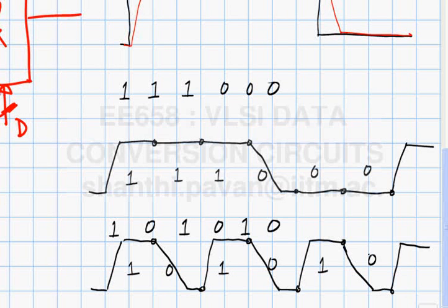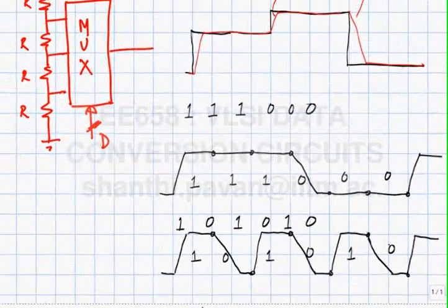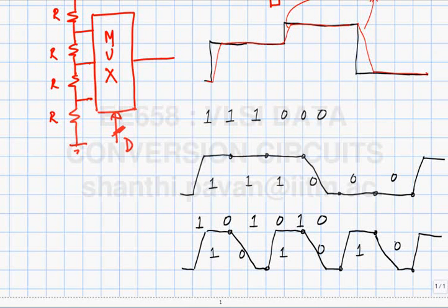So finally you want the DAC to be a linear system, right? So the output voltage must be, what is a linear system? If I put in a waveform x1, the output was y1, and if the input was x2, the output is y2. If I put x1 plus x2, I must get y1 plus y2. That's what a linear system should do. Let's figure out if this is a linear system.